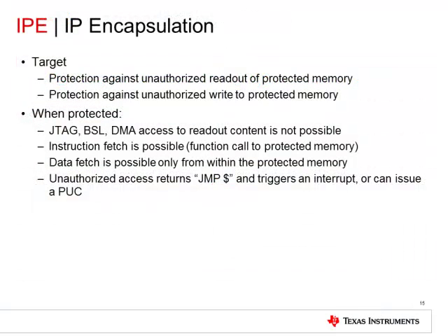IP encapsulation. Manufacturing trends have changed greatly in the past decade. It is now not uncommon to program a device in different stages of end equipment manufacturing involving different third parties and geographic regions. In some cases, it is desirable to protect a certain code segment from external access via JTAG or BSL while still allowing a third party to program the device.